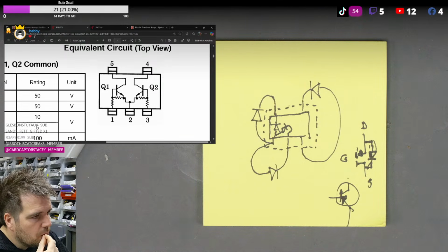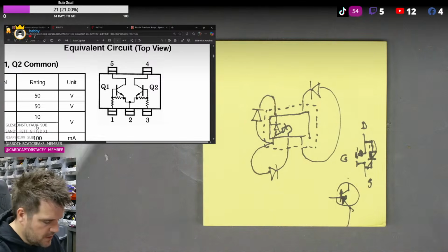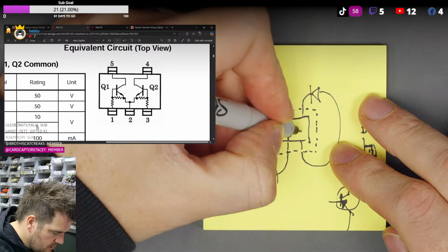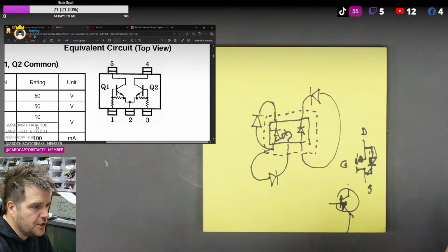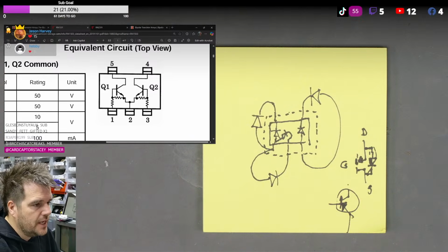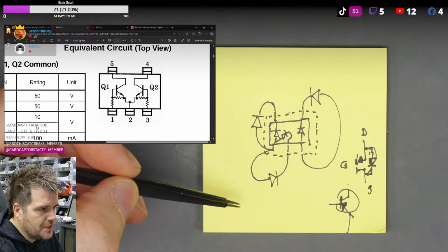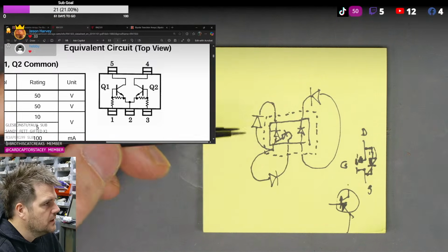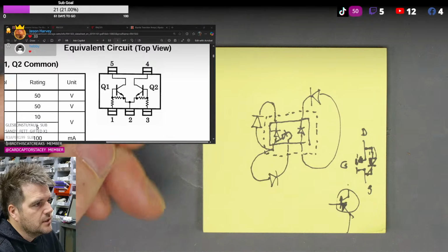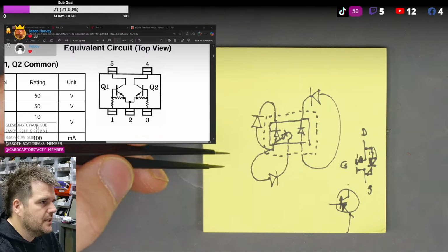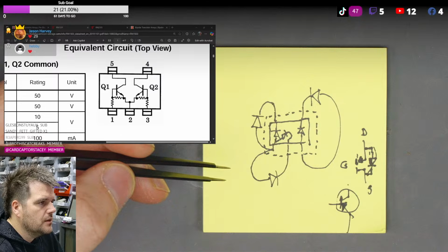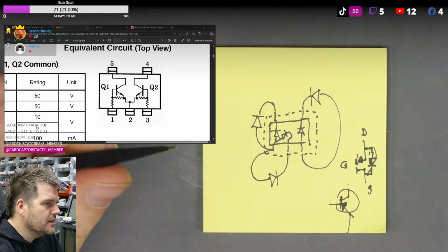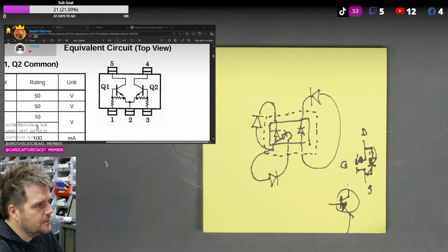But the one going up won't. And the other side has ultimately this going in. Op amp, I don't think there'll be an op amp, by the way, because it's got a Q on. An op amp would normally have a U designator. It's not saying it won't be. I just can't imagine it being an op amp, and it's part of the voltage regulator circuit. So this, well, saying that, maybe, because it's connected to the Zener diode.